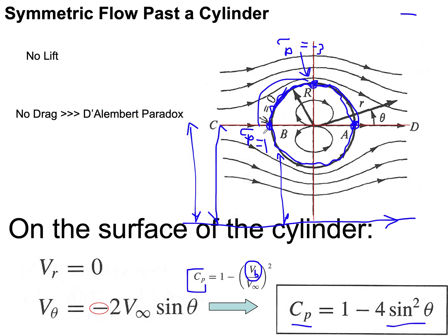Yeah, let's do it actually. So I now have streamline A, and I have streamline B, and what you get, if you look at the distance between the two streamlines, is a constant mass flow rate between those two streamlines, because mass flow rate does not cross a streamline. So that's my streamline.